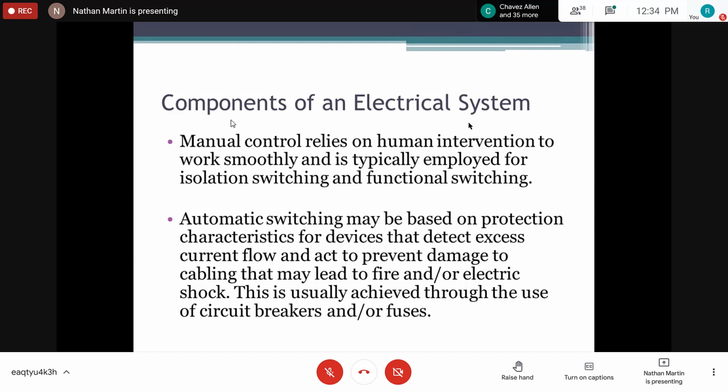And then they would have to go and manually look for the fault, patrol the line, look for the fault, and then call control and tell them to close the recloser. So most of the time it's used for protection purposes. Most systems that have an automatic lockout mechanism or switching mechanism are mainly for protection purposes.